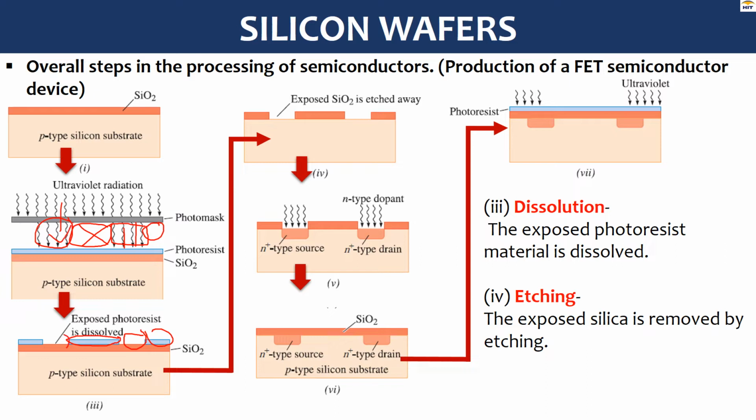So we can see here that our photoresist material has been removed. So we now dissolve the photoresist material here. It is actually dissolved. So that's the dissolution. When your ultraviolet passes through this photoresist, then it causes dissolution to occur on this substrate wafer.